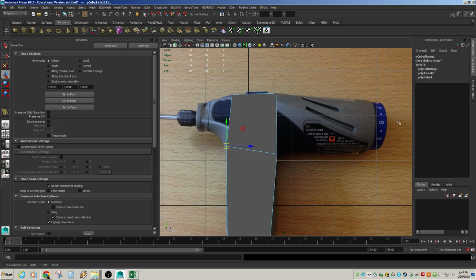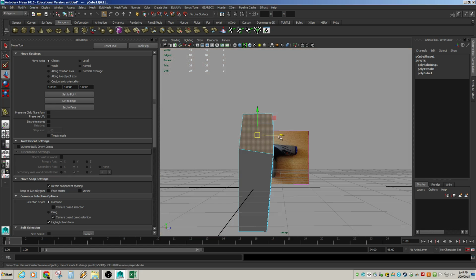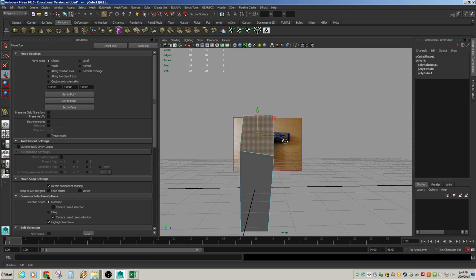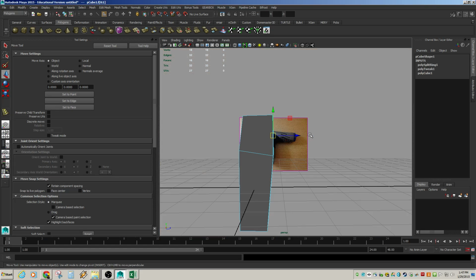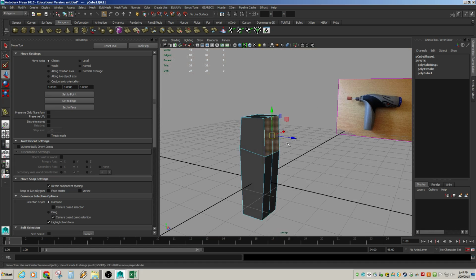I would probably extrude this out from behind, and so I'm going to show you what I've been doing from this direction. If I go to face and I drag select, I'm going to select both the faces on both sides of this, plus the face that is diagonal there, right? I selected all those, but then if I hold Control, I can deselect the ones I don't want. So now I just have those two faces selected. That's a little selection trick you can try.